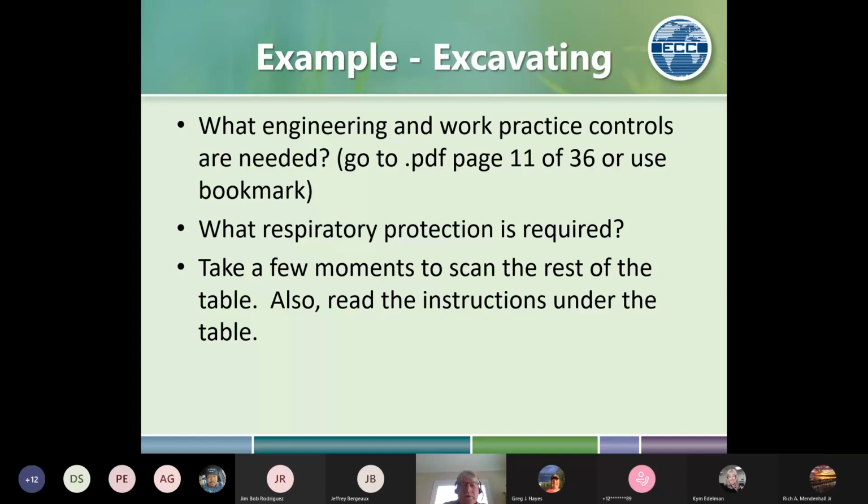It also has to be under positive pressure, maintained through continuous delivery of fresh air. Most standard HVAC systems on heavy equipment do not have that, although I think there are some manufacturers now that are including that since the standard got promulgated. But there is retrofit equipment that will maintain a positive pressure. And also the air intake has to be filtered with MERV 16 or better.